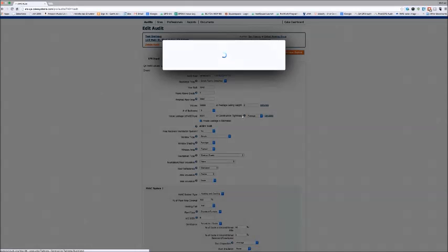We allow you to do some calculations to do an estimated volume just based on the average floor height. You can calculate what the volume would be. If you have 9-foot ceilings, it's going to be higher. Number of bedrooms, house leakage. If you're doing a blower door, you can get the actual house leakage. If you're not doing a blower door, we let you pick from one of the preset criteria for how leaky that house is relative to the parameters that we define here.